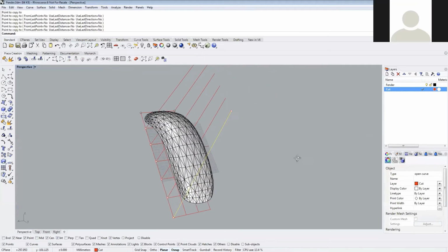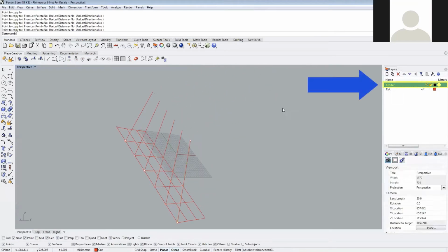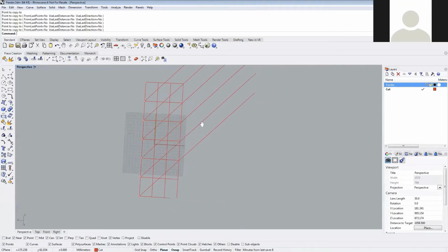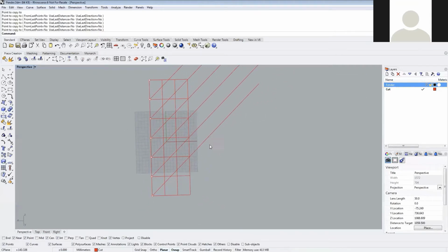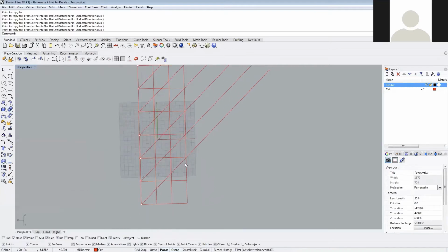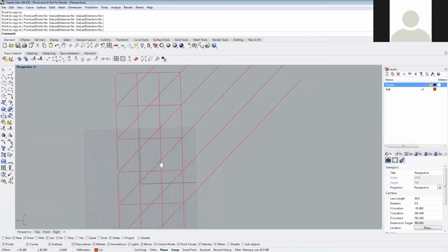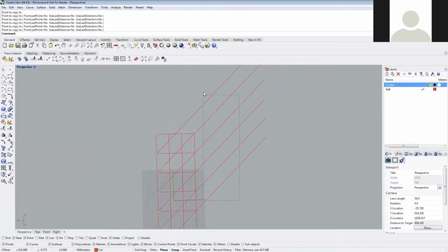The other benefit to this is that we're going to turn off our mesh, and we can actually examine the splitting planes here, or the cutting curves. So what we want to make sure is that we don't have all three layers coming together at a common point. So this allows us to examine where all of these curves or planes are going to intersect. And right here we've got, it's very close. Same thing over here.